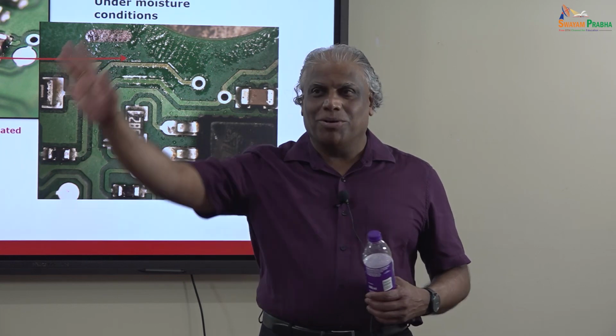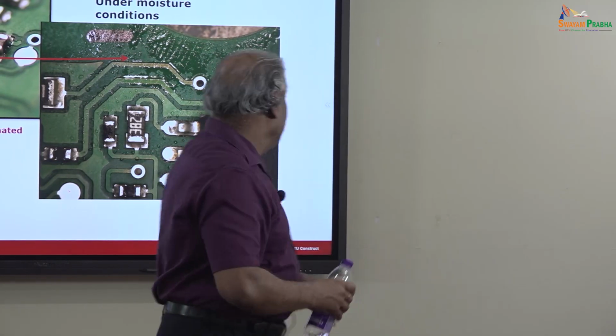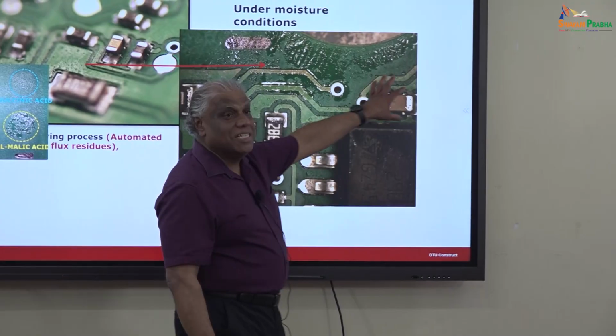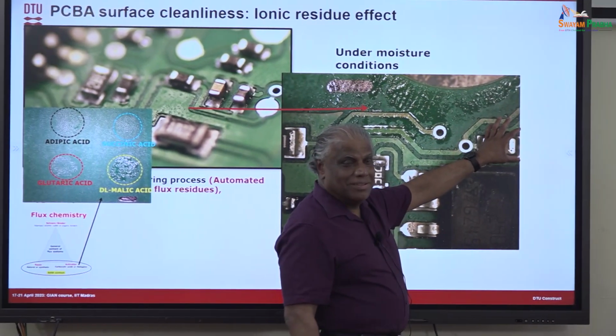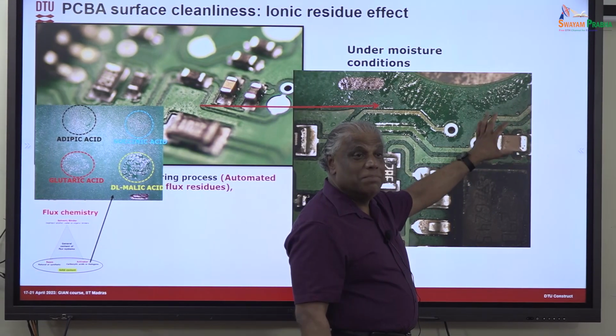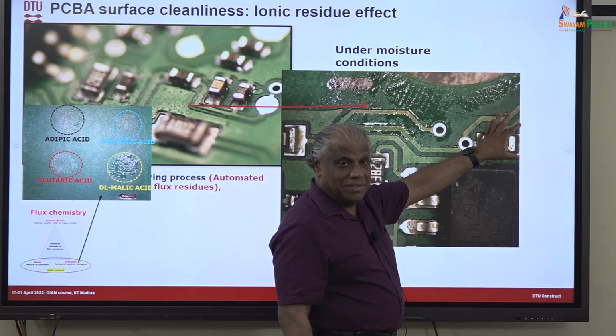So you have the whole circuit, and then the PCB design people will be able to say, on this PCB, this is the sensitive area. That they know from the circuit. That is, this area should have a very high impedance, so any stray current in that area is problematic.